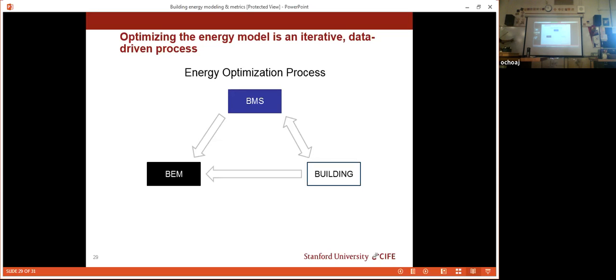So I can figure out those curves, and I can set the system because I want to optimize the heating of this building to get it to 65 degrees. And so I can run a software algorithm on the control for this unit that's going to turn it on at different points and turn it off at different points, measure the actual output, and then we'll just cycle through. So for a week, this thing will turn it off seemingly random.